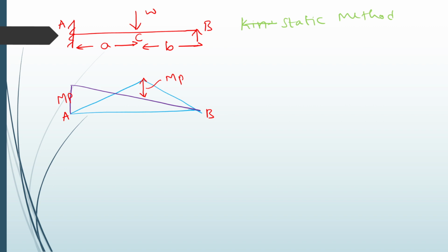From this bending moment diagram, since the static bending moment at C is greater than at A, the plastic moment at C is greater than at A. So the plastic hinge will first develop at C and later at A. The structure will then convert into a mechanism and ultimately collapse. During collapse, the moments at both A and C will be MP.